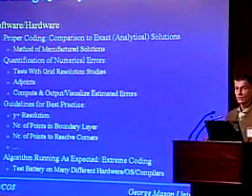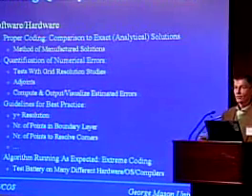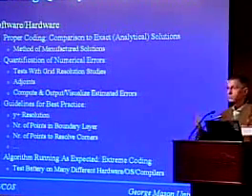For example, in the aerospace industry, you will never build a mesh that is going to compute drag on a wing if you don't have a Y plus resolution of 1, okay, in the boundary layer. And then there are norms and accepted standards as to how many points you want in the boundary layer and how they are distributed there, and then how many points you want if you go around the corner or something of that nature.